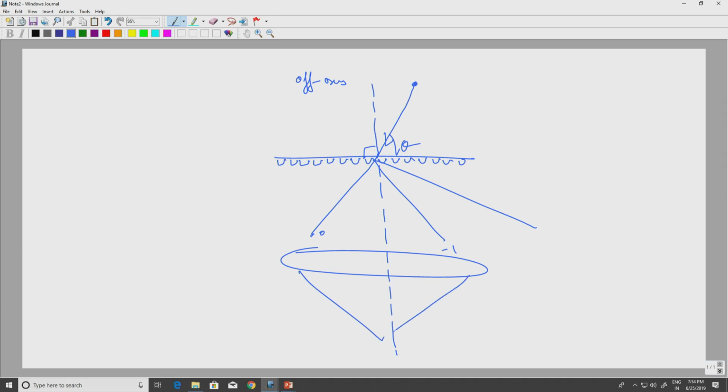So now because of this angle, I am able to bring in both my zeroth order and my first order here. With this off axis illumination, I will be able to image even the pitch that are greater than, right, the pitch resolution.